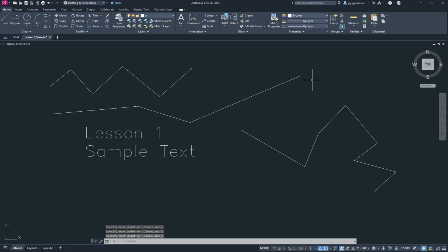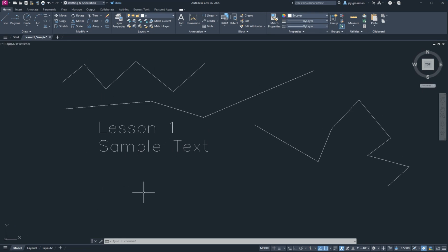In AutoCAD, the spacebar and the enter key are the same. Every time you hit the spacebar, it's just like you hit the enter key for any command you're running. I guess not if you're typing outside of AutoCAD, but within AutoCAD, the spacebar is equivalent to the enter key. Originally, we did a lot of text input for commands, and the spacebar was easier to find than the enter key, I guess. Easier to hit with your thumb as you're going along.